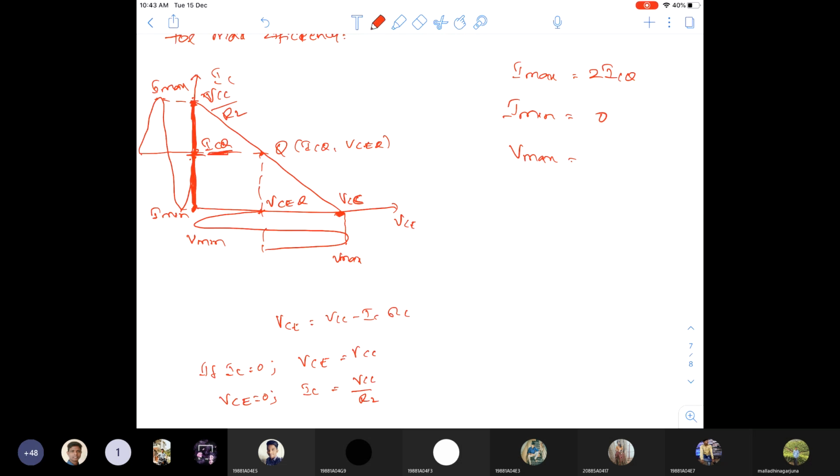Okay, VCC. What is Vmax? VCC. Okay. Next, what is V minimum? What is this point, V minimum? Zero, sir. Zero, right, very good. V minimum is 0, I minimum is 0, Imax is 2 ICQ, Vmax is VCC.